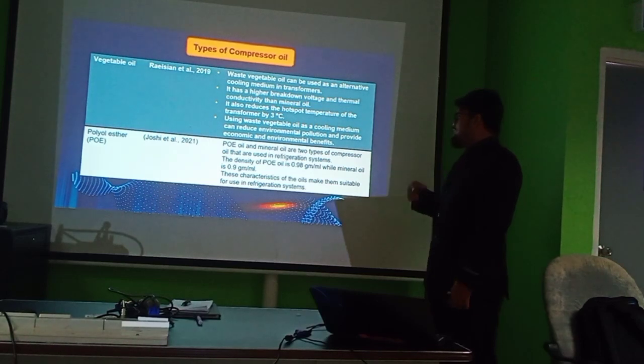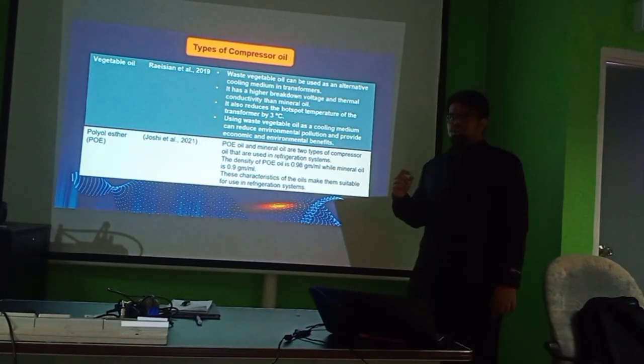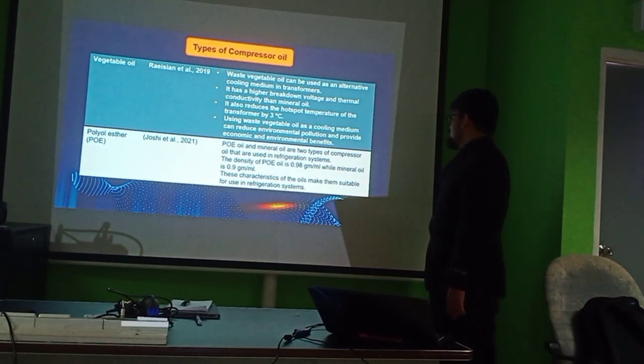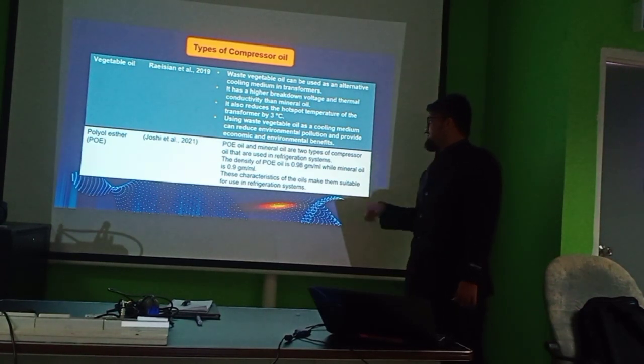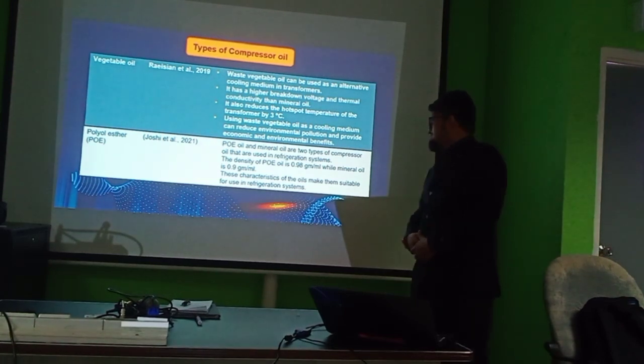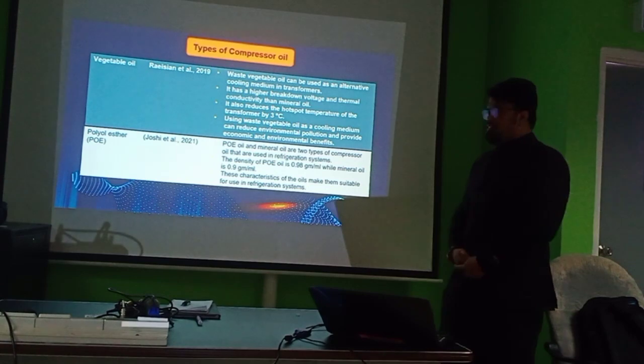They found the density of POE oil is 0.98 gram per milliliter, while mineral oil is 0.9 gram per milliliter. And this characteristic of oil makes them suitable for use in refrigeration systems.